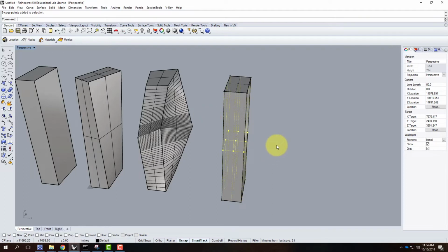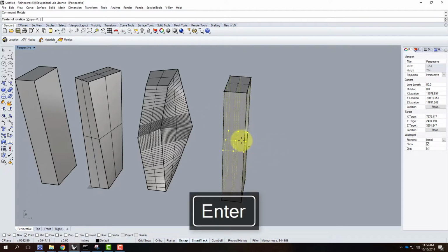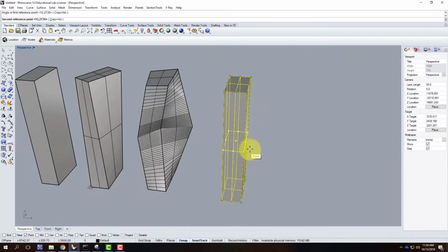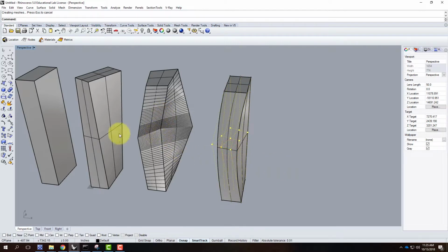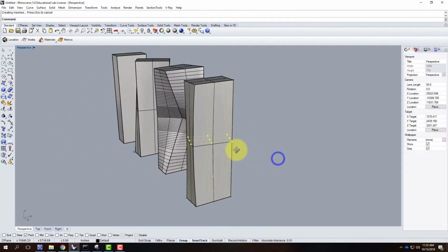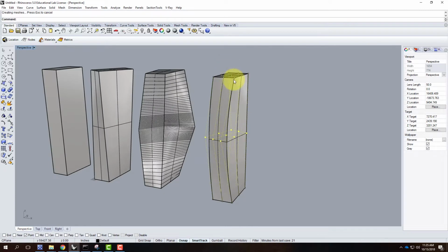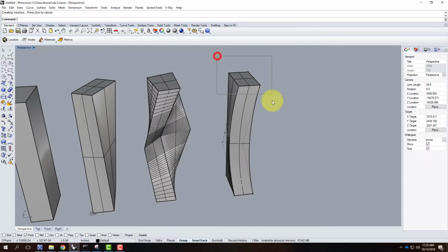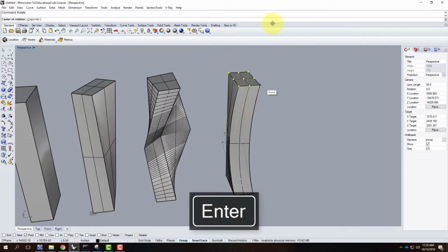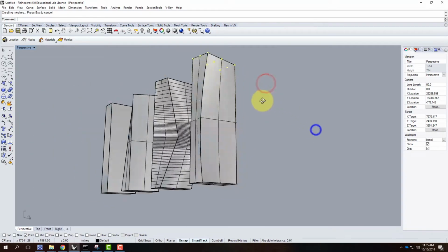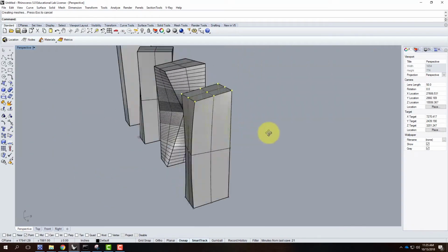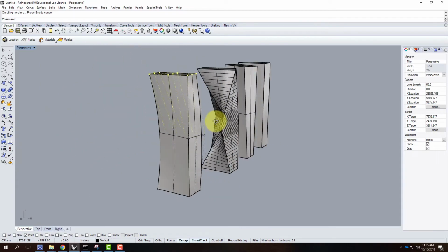Let's do the same rotation that I did before. I started with the rotate, and I rotated from here to here, and I rotated this way. Notice that when I rotate, it's no longer giving me an angle like it did here. Because my curvature is set to 2, it's giving me a curve between those points. Likewise, I could come up here to the top. I could rotate. And I could rotate this one back a little bit, and we can exaggerate the curve. So it's actually curving the shape underneath.